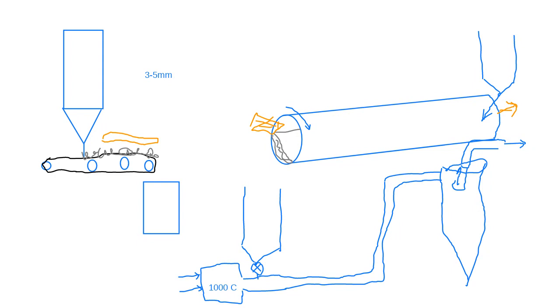Anyway, here particles come in. By this time they're dry. It's hot gas with dry particles, and this enters tangentially into this cyclone. So it creates a swirling effect, and you get centrifugal force on the particles so that they fall down the inside of the cyclone.